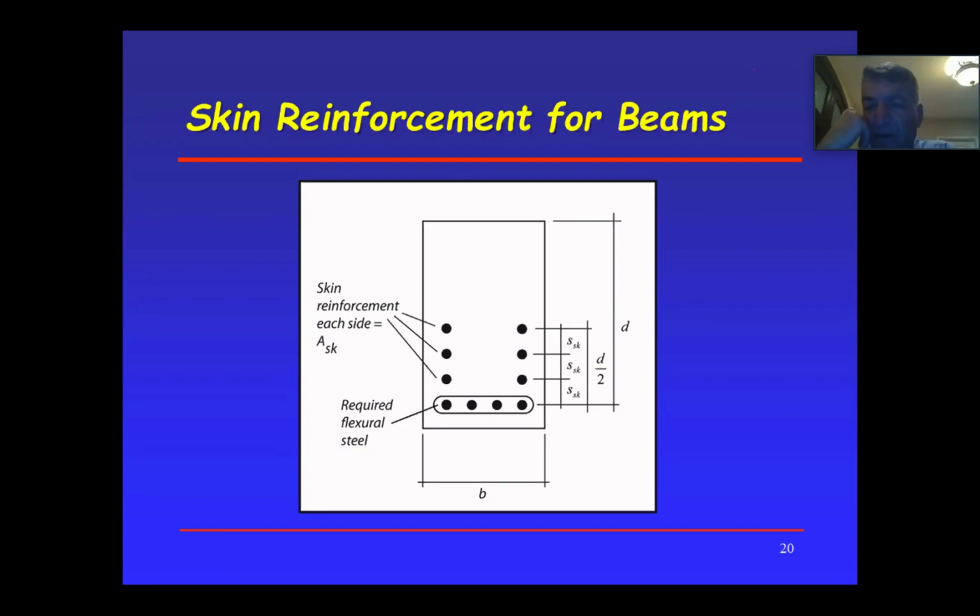What happened on the ground floor? You need an entrance to the parking garage. You cannot say I'm going to enter between those 9 foot columns, 9 foot space. No, you're going to at least delete 1 or 2 columns, right? So if you delete 1, then your span is 18 feet. If you delete 2, then your span is 27 feet. Okay, that's along the span. And that's on the first floor.